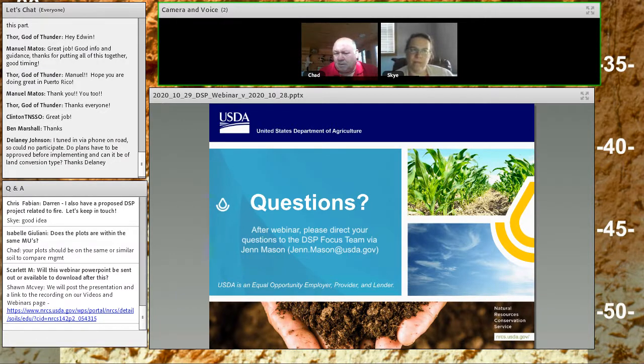The other part, to continue on that, there's a question on running KSAT on a change over time. Most things in soils don't happen quickly, so look at a 3 to 5 year time frame before you return on a repeated measure study. There is no reason to go out the next year. You need to allow some time.